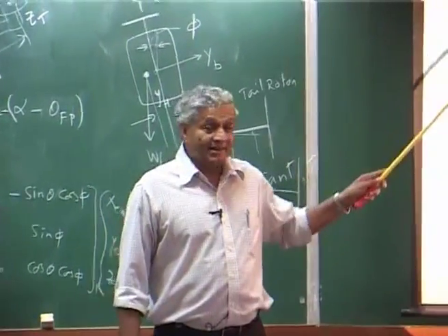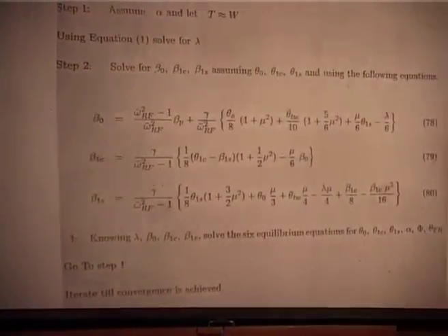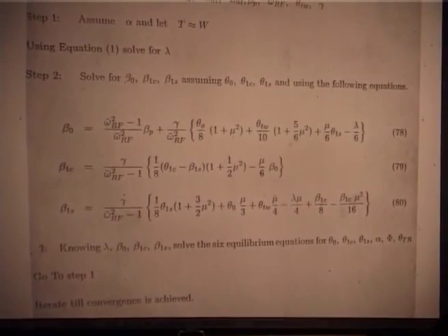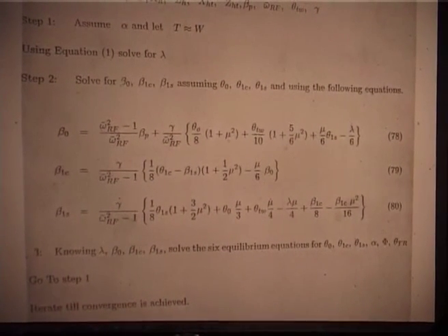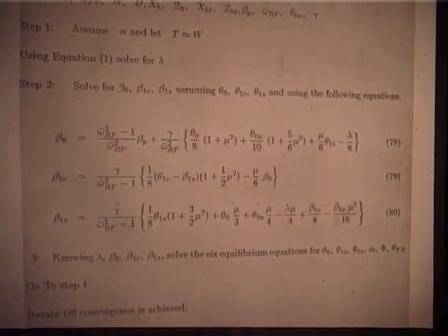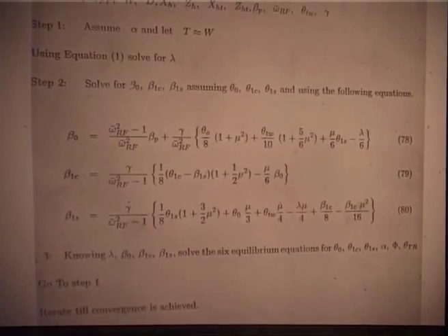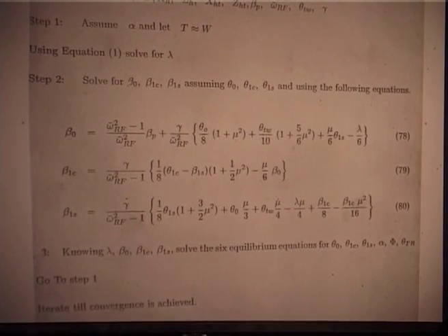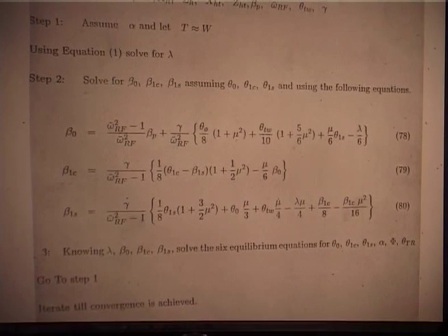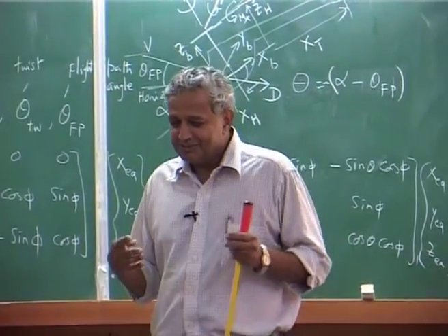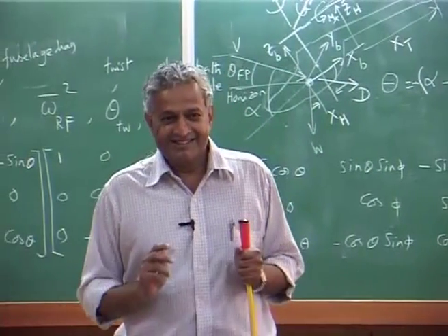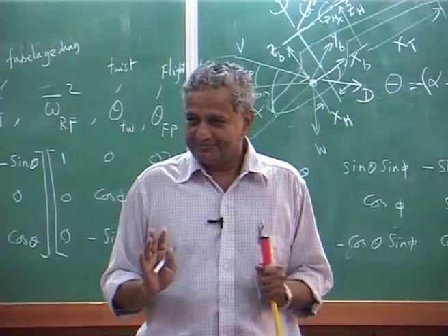Now, I am just extrapolating the complexity. We made several assumptions. One is in the inflow, uniform inflow, it is not uniform, it is variable. The second one is flap, who told you only first harmonic, I should have all the harmonics, then I should have lead lag motion, I should have torsion motion. That means your problem gets complicated. And you should have stall, you have reverse flow effects. When you start adding everything, the problem becomes sometimes intractable. It is a complicated problem.